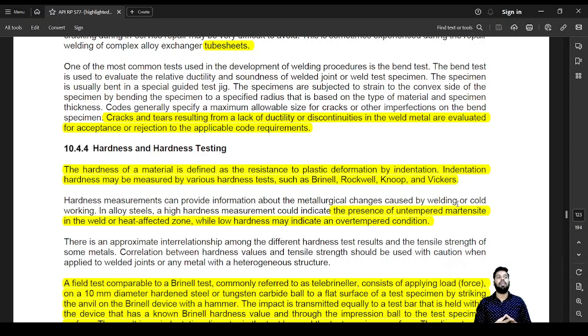Okay, you understand this? Because if the material is more ductile, then if there are any foreseeable circumstances where the material is subjected to heavy loads, the material is going to bend but not break. But if it's not ductile, it is brittle, and if it's brittle, instead of bending, it will break and your material would fail easily.